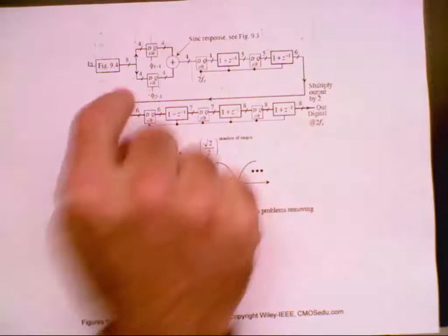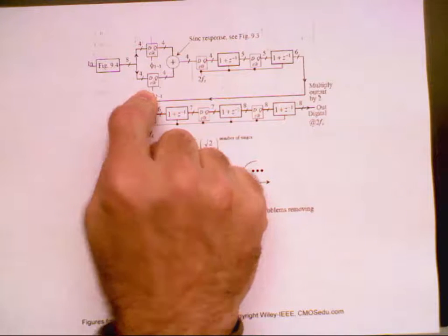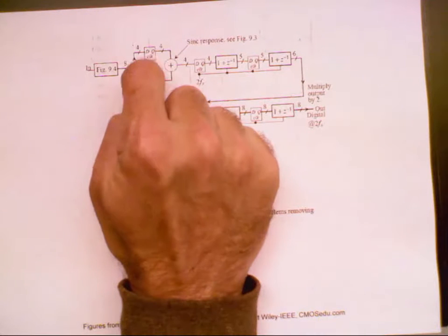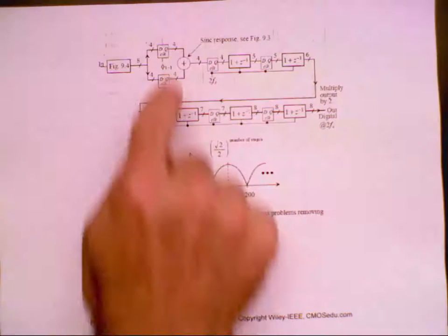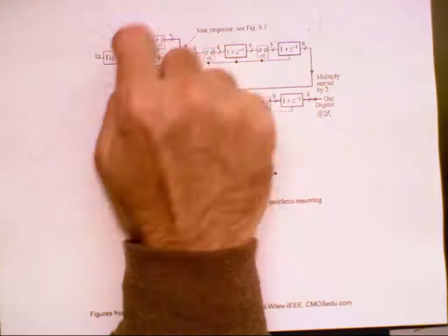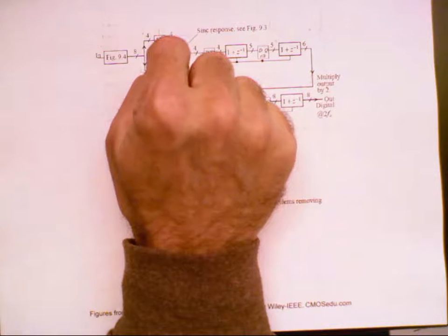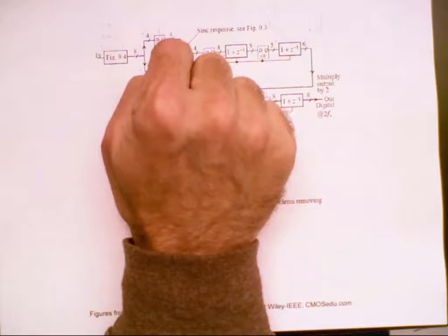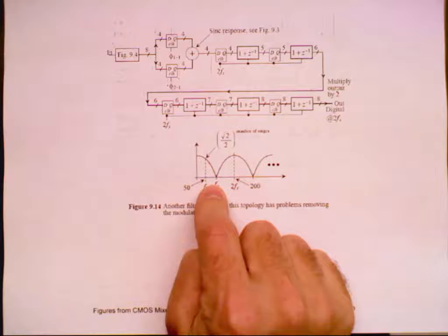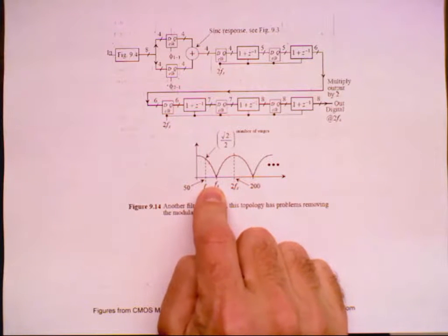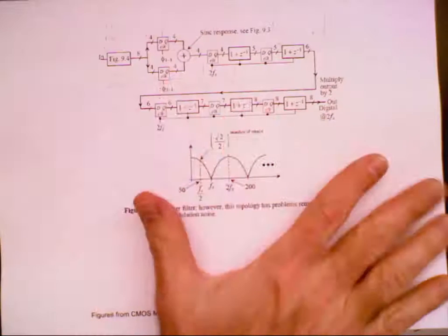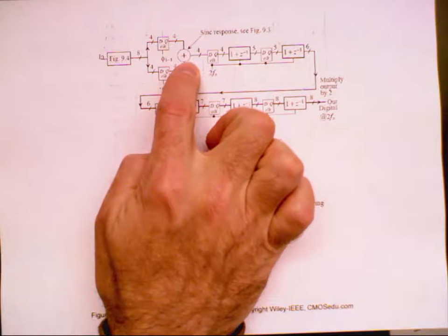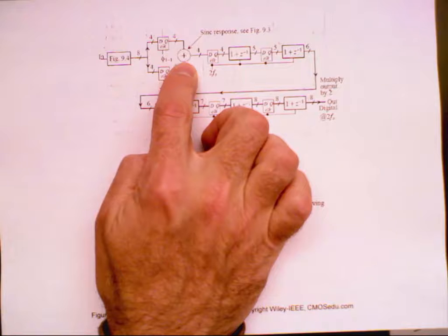So here's a simple example where I take 4 bits out, and then the other cycle I take 4 bits out, and then I add them together out here. When you add these 4 bits with these 4 bits, that's a 1 plus z to the minus 1, which has a frequency response that looks like this. It's an averager. It's going to be wider bandwidth than what we had before, but it's going to influence your frequency response, and then you use the filter that comes out.